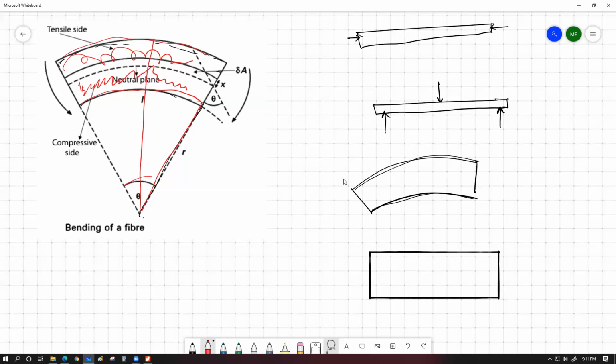And there is a way. The reason bending actually causes such a high breaking tendency is because of the mismatching of stress within the same specimen over such a small thickness. For example, let's say this is a cylindrical wire, maybe 1 centimeter in diameter. If we bend a 1 centimeter material in this fashion, the tensile stress over here is going to be pretty strong, and the compressive stress over here is going to be pretty strong as well. So within a very small thickness of material, you're going to have two opposite types of stress built up, making breaking much more likely.